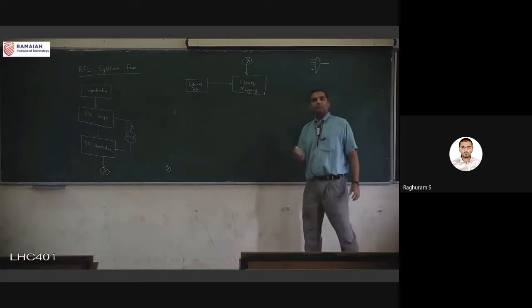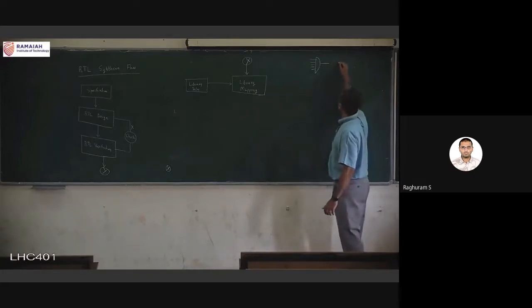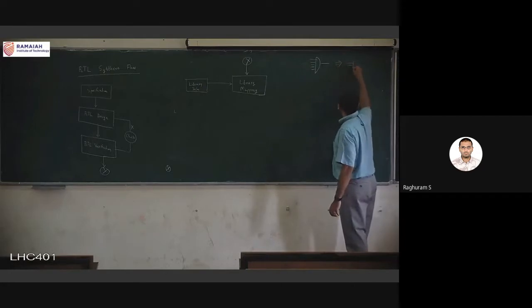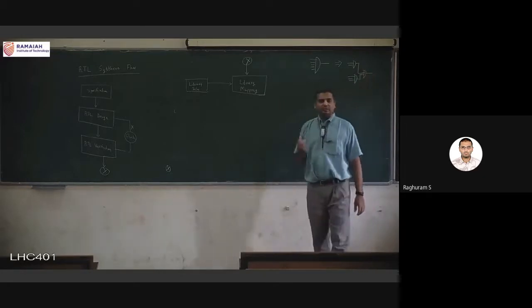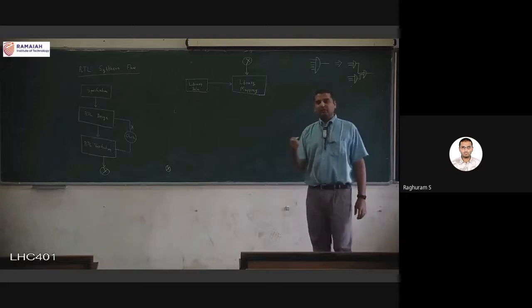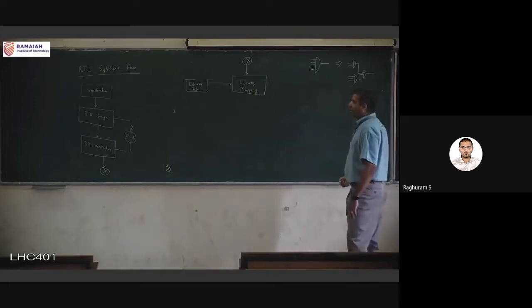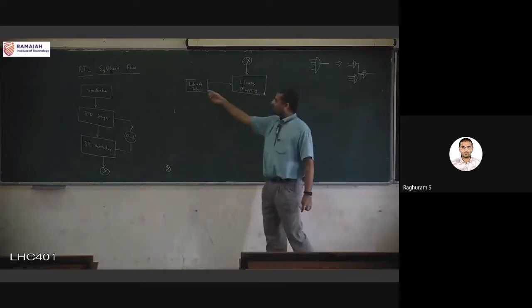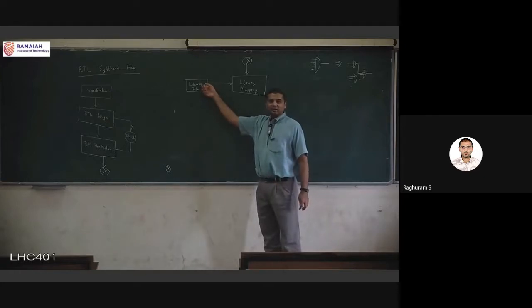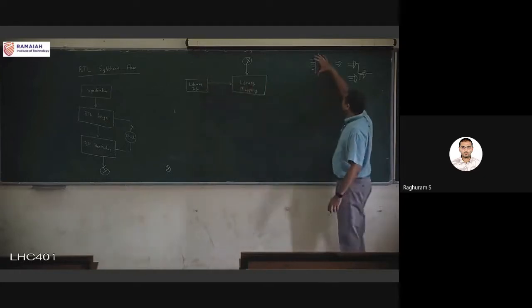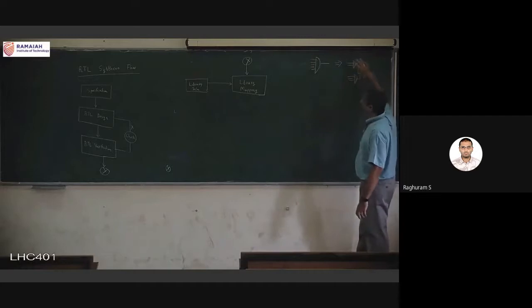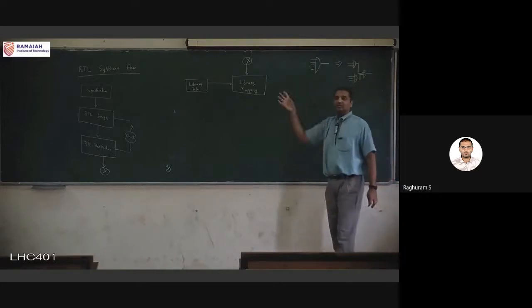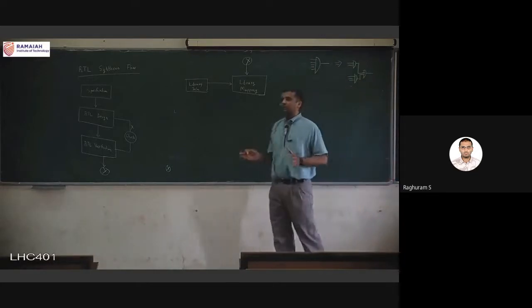So we have to produce that transformation. This might be a very simple conversion. For example, 2 input and 3 input gates are there in my library. So instead of one 5 input AND function, I will look at my library, see what other gates are there, and try to transform the 5 input function into available gates. That is the mapping, again completely based on software tools.